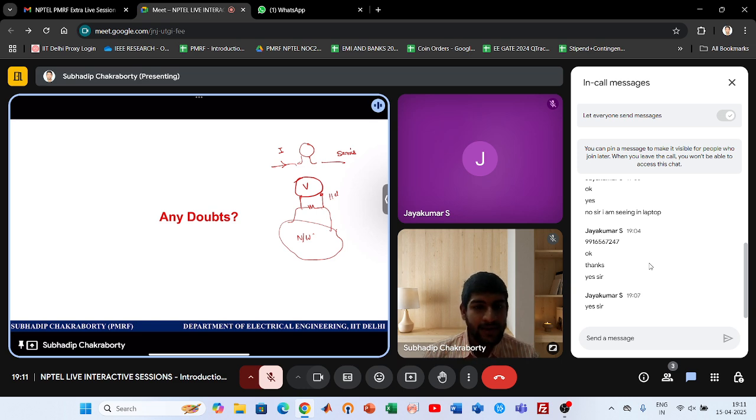Now tell me one thing, if you want to measure the current or the voltage without any loading effect, because you know that if you want to measure some current, let's say 5 ampere, you need to connect the meter also, right? In the lab also you connect it in series to the branch through which you want to measure the current. But this meter also has some internal impedance or resistance, which you can simply model. So this meter will also have some loading effect on the network.